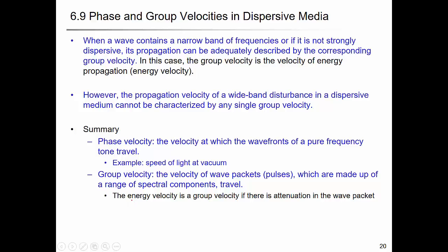So just be aware that there's a difference between phase velocity and group velocity. And when you have a measurement of the acoustic signal, you can do the Fourier transform, divide it into each frequency band, and get the phase velocity of each frequency band.